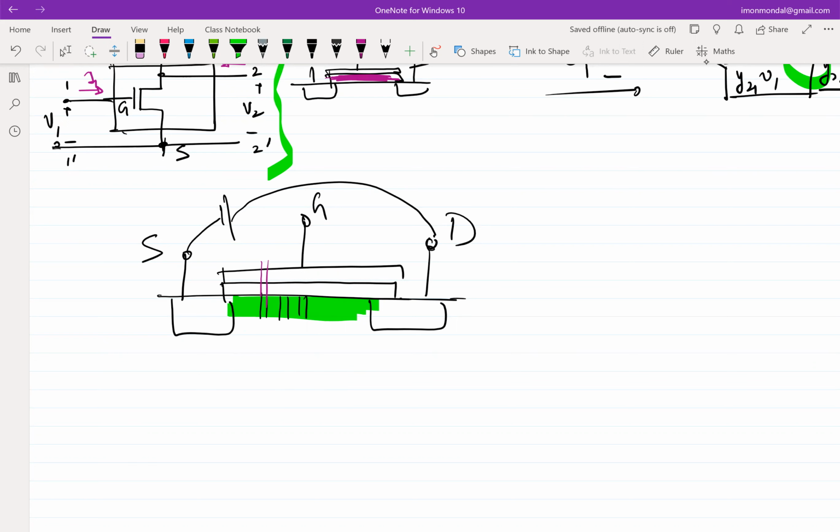So obviously, we'll have to take into consideration that there is a voltage profile along the channel. So let's take that into consideration. Let's say there is a voltage profile. You had applied a certain VDS, so the voltage profile will probably decrease between a maximum at the drain and a minimum at the source. Even though I have drawn a straight line, it need not necessarily be the case. It can be any profile. All we know is that it will be maximum at the drain and minimum at the source. Okay, so let's say that around a distance x from the drain, I'm interested in this level.